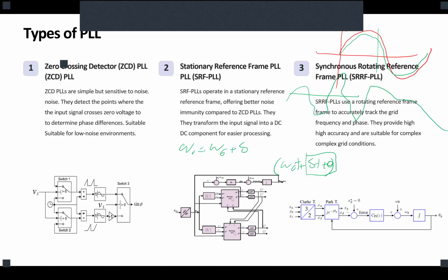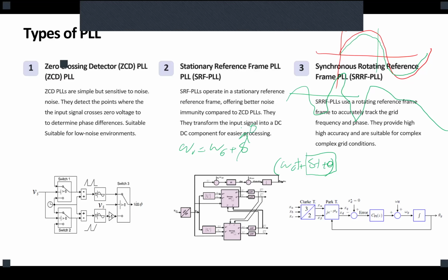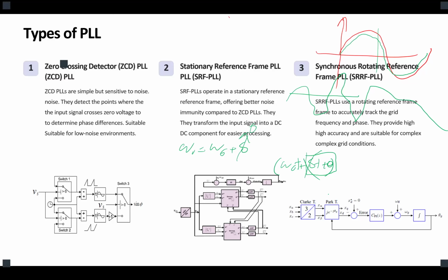Is that clear? Yeah. So why do we need this? Because from what you said, the PLL only controls the frequency. The PLL would make this delta go to 0. So now there is no variation, and you can trust your control system on active power injection. So we need to be synchronized because of that. Are we good? Did that answer your question?